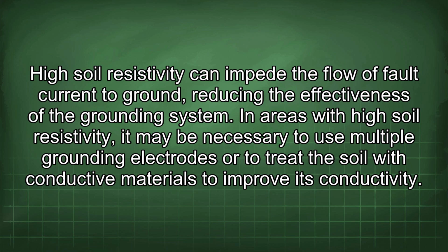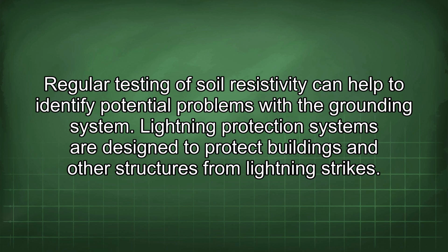In areas with high soil resistivity, it may be necessary to use multiple grounding electrodes or to treat the soil with conductive materials to improve its conductivity. Regular testing of soil resistivity can help to identify potential problems with the grounding system.